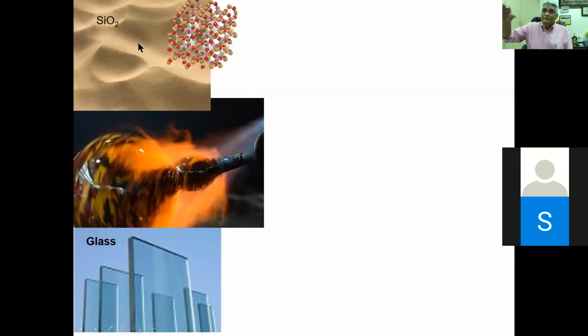Okay, but the glassy form of any material is possible if you take it to its melting point. Zinc oxide, barium titanate, which is a ferroelectric material. So you take barium titanate in its powder form or any form, heat it to its melting point, quench it to room temperature. So what is happening during the quenching process? When I say quenching, it's rapid cooling. I melted the material. So silicon dioxide is in its molten state. That means its atoms are free floating, and by removing the thermal energy, I'm not allowing those silicon dioxide atoms to form into a regular crystal lattice. Is it not?